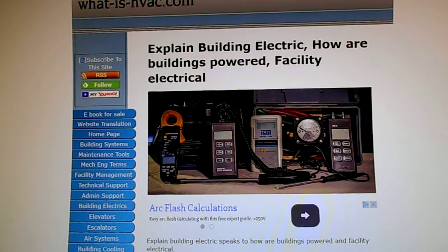The house voltages are provided by neighborhood transformers that lower the voltage of a phase of the distributed three-phase. The neutral is directly connected to the three-phase neutral. Socket voltages are only 120 volt, but 240 volt is available for heavy appliances because the two phases oppose each other.